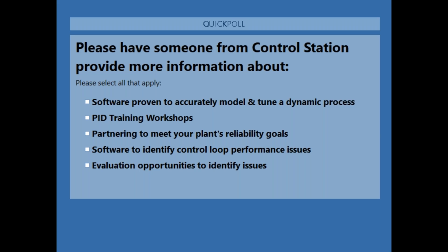The next question is: when you say reduce your integral, if my integral is 1 minute, am I making the number smaller or bigger? What I would say is reduce your integral effort. Be less aggressive with your integral. Integral can be above the line or below the line. If it's above the line in the calculation, it's integral times the error, so a bigger number gives more integral effort, and you want to make the number smaller.